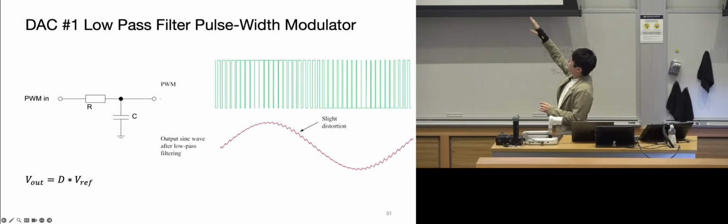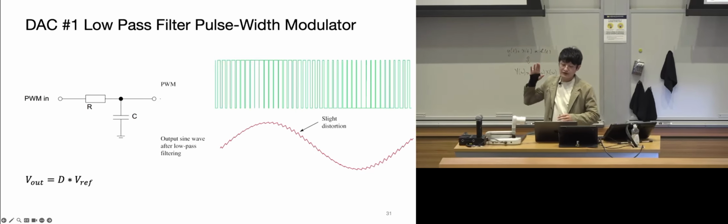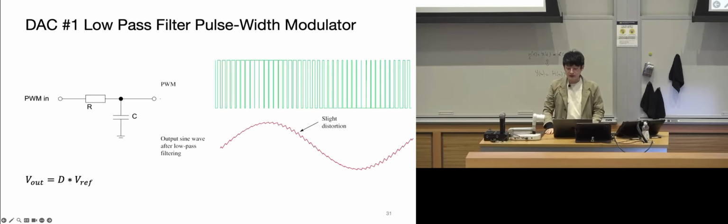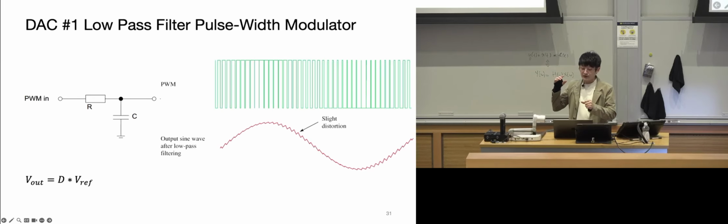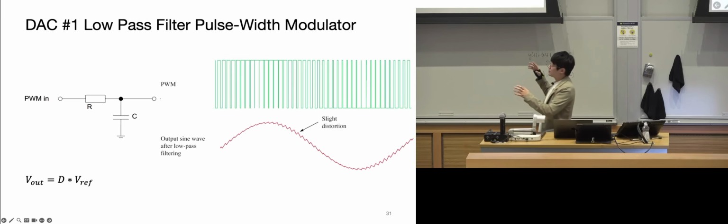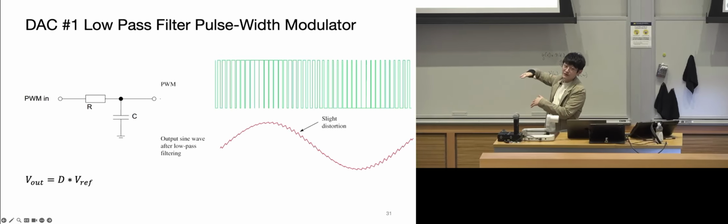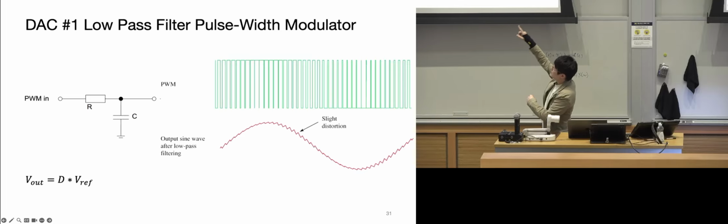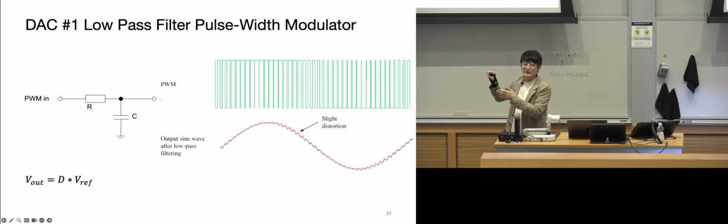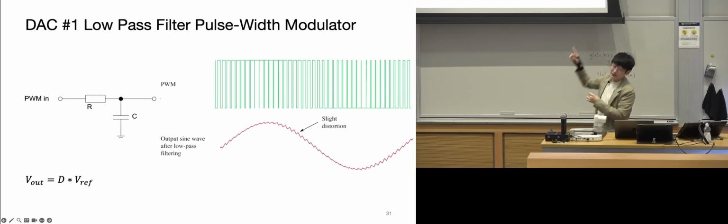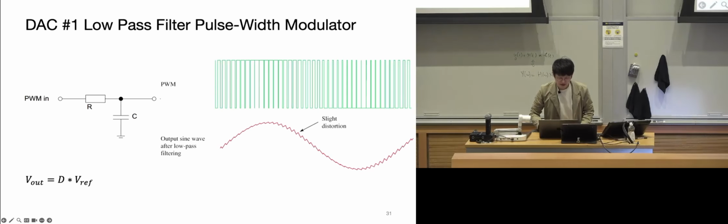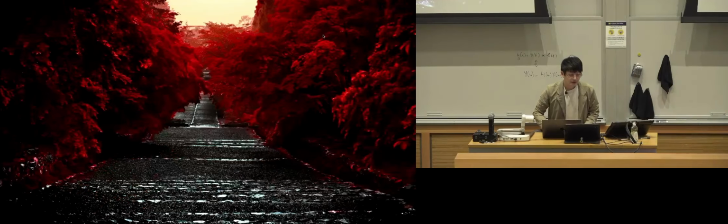The reason you see these spikes is because this type of DAC is a PWM signal that passes through a low pass filter. So only the rapid on and off shifts of the PWM signal are being kept. The remaining part of that signal is just cut off from the output. So you have essentially a value corresponding to the PWM duty cycle you set at that moment, and you will have a signal generated like this. We also have a circuit that we put out.